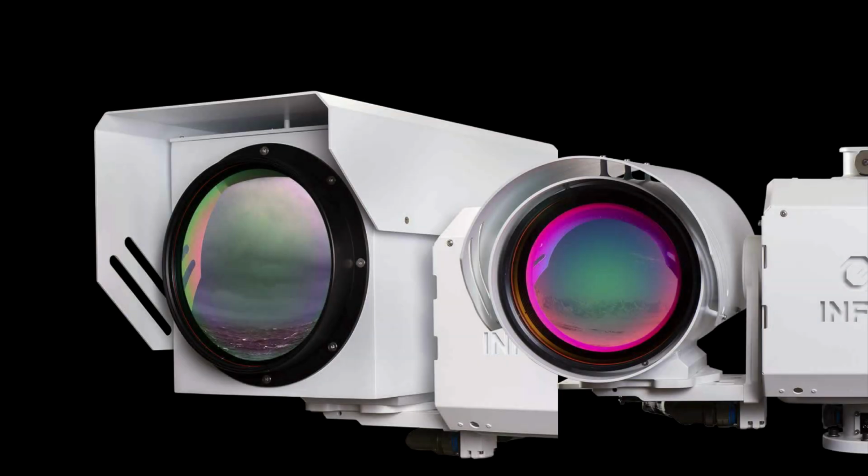Now, it is important to know that the thermal sensors use lenses like the visible cameras. Just in this case, the glass material for those lenses is chosen to be transmittive to the LWIR range of wavelengths. Typical material for this is germanium, silicon, zinc sulfide, or chalcogenide.